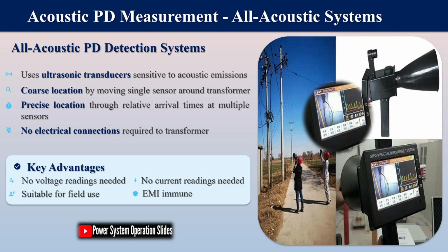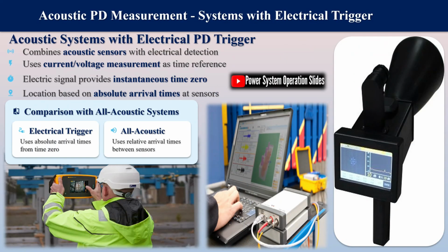These measurements utilize UHF antennas inserted into the transformer tank through oil sampling valves, with the metal surface of the transformer tank acting as a natural Faraday cage to filter out electrical interferences from outside. The high-voltage bushing C1 capacitance further enhances this filtering effect by acting as a low-pass filter to reduce electrical interferences from outside the tank.